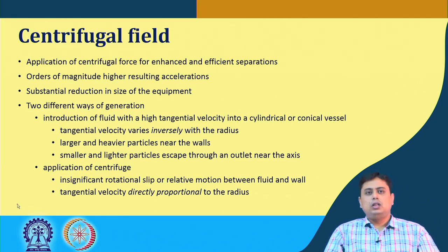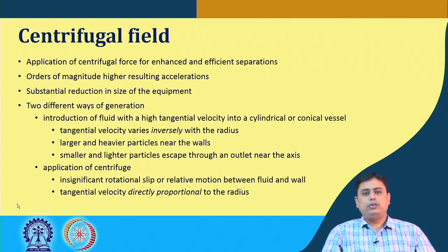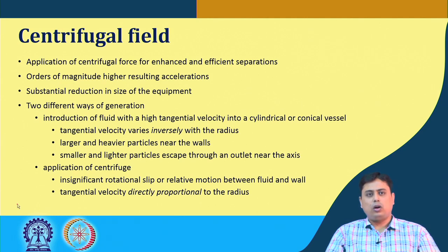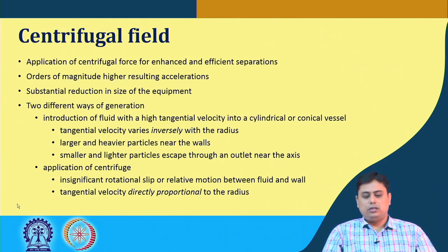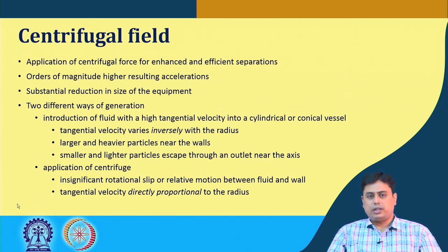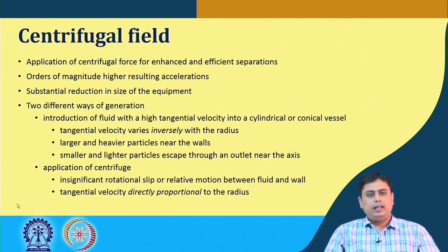Now, application of centrifugal force enhances the separation by orders of magnitude compared to the gravitational settling cases. So, it results in very high accelerations in the field that lead to efficient and enhanced separation of particles.